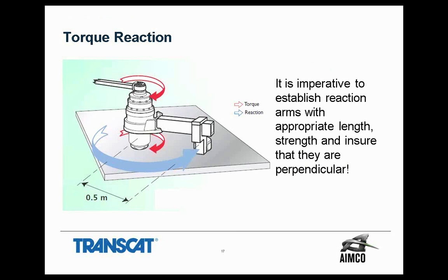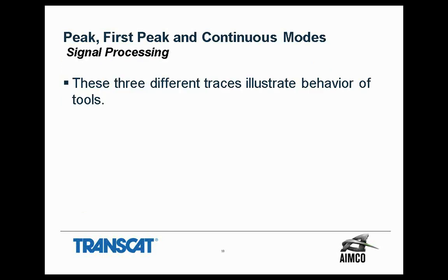Again, I sound like a broken record talking about torque reaction, but torque reaction is extremely important. If you don't plan for it and deal with it, not only are you going to risk somebody getting hurt, you're going to damage your multipliers. You'll break teeth off, you'll damage gears, and then you'll go back to the manufacturer with a complaint, and they'll tell you, sorry, we can't do anything because you experienced excessive side load, and that's what broke it.